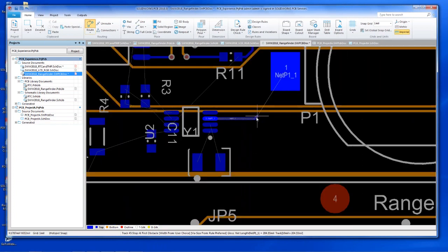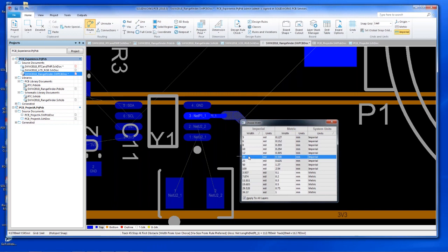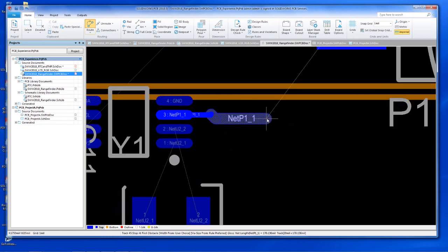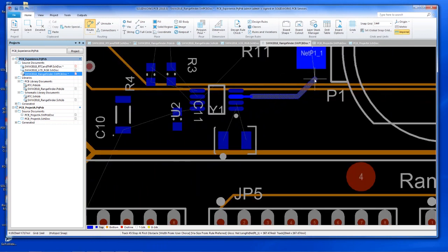So those wire modes I mentioned for schematic, again, they're the same in the PCB tool. There would be our arc routing mode, we would have 90 degree, and then you have full orthogonal as well, okay? Which can be helpful when routing shortest distance for printed circuit boards. So we'll go ahead and put in our first corner, and we'll now switch this trace width to something doubled in size, okay?